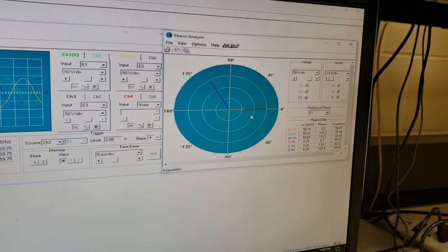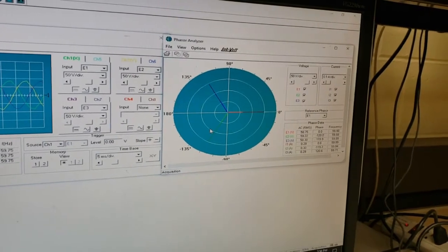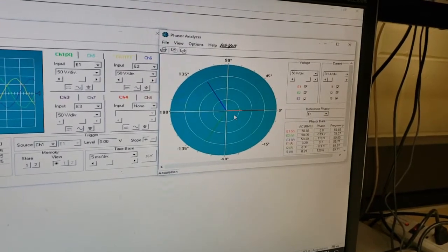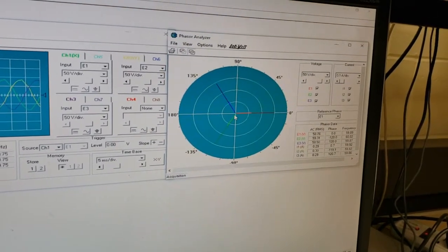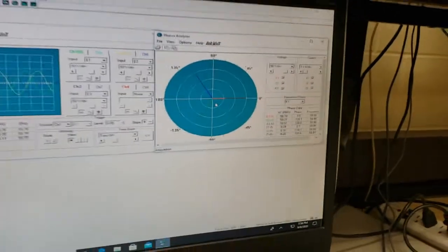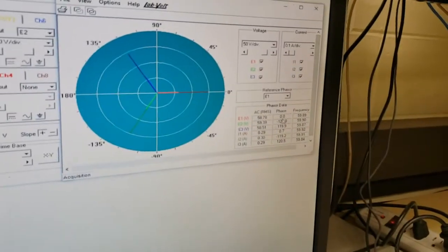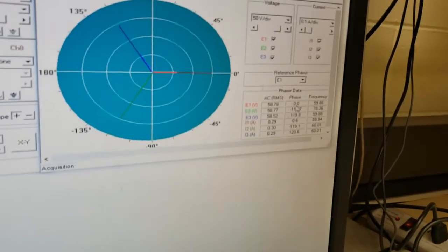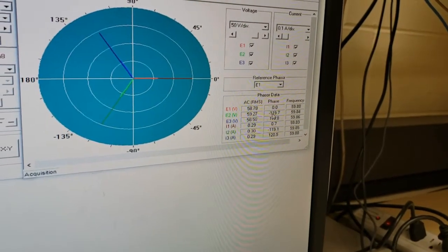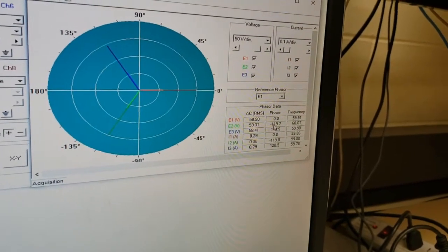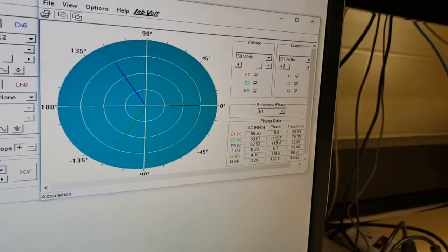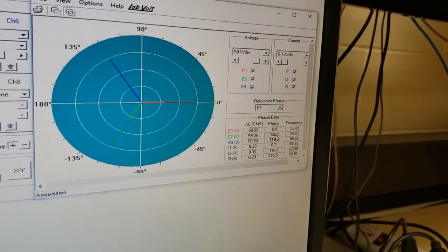So here we have resistive loads, and so indeed we see that three-phase nature. Resistive loads, and they're all equal, so we see that three-phase. And also because they're resistive, as you should have learned from the lab so far, the voltage and current are in phase with each other. Okay, so that's that. Also, one last thing I'll note is you can see the ABC sequence over here with the voltages. This is A, and then minus 120 degrees. This is the second voltage source, and then minus 240, which is the same as plus 120. And so, if I'm remembering this right, this is the positive ABC sequence.